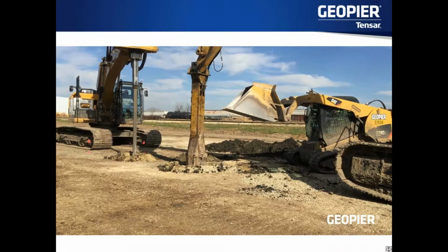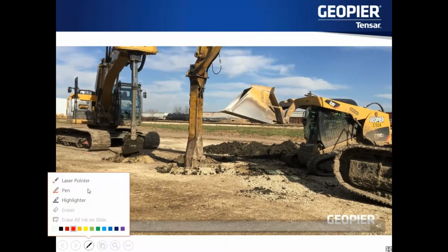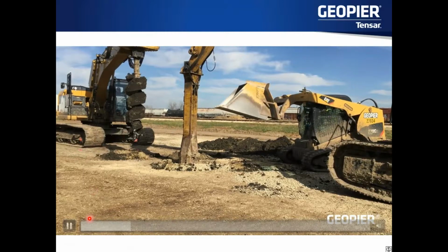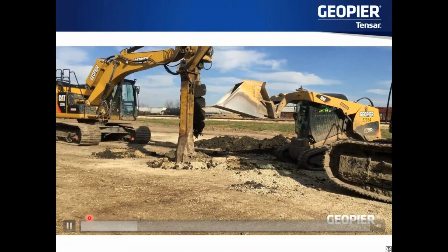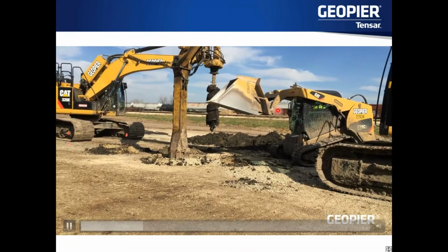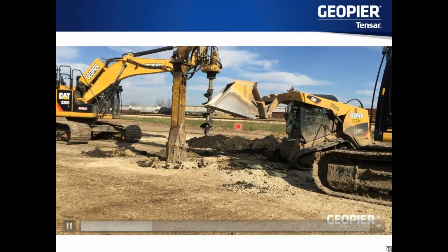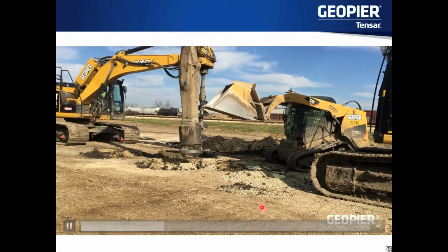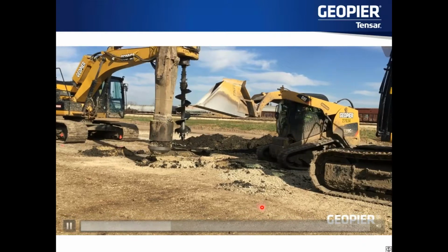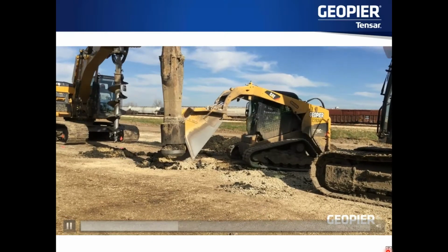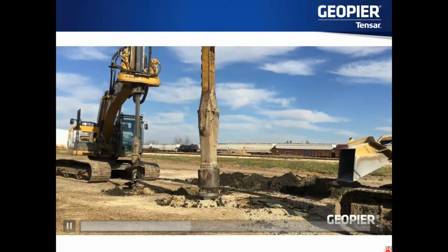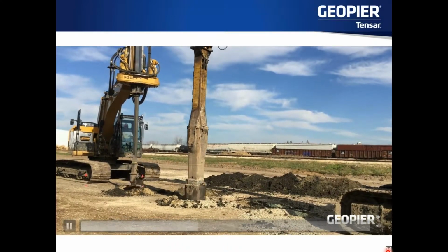What we see here is we've got our pre-drill rig over to the left, and you can see this is excavating out that cavity, maybe a 30-inch element. And then our tamping rig is over here to the side with the skid steer that's funneling stone to and from the cavity to build these elements. So he's just completed a lift, and then we're introducing the aggregate, so probably a CA7 type stone, and then we'll trip down back into the hole and compact the next lift of aggregate.